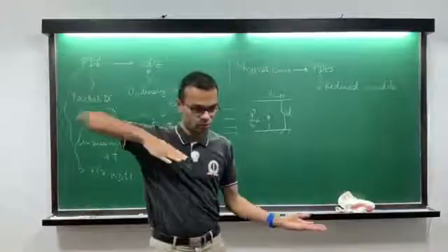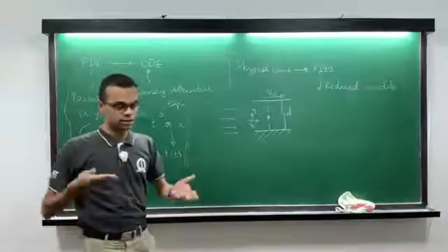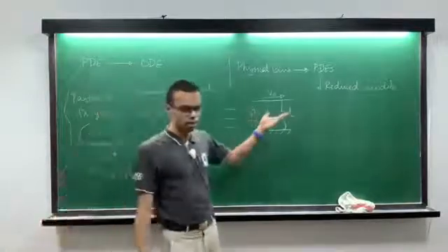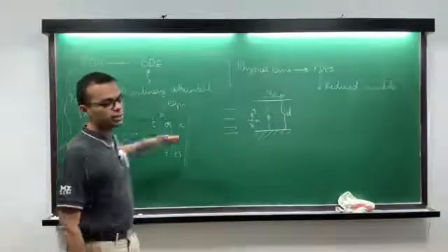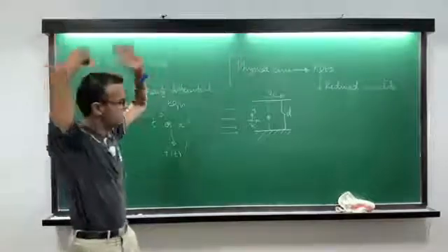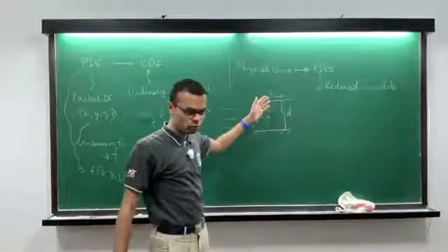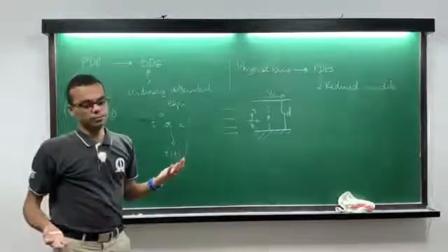Okay, so I'm continuously moving this top plate, but I'm not interested in the transients. Presumably transients happen very quickly. The nature of the fluid, I know that a priori, and I'm not interested in the transition. I only want to know what the final profile is as t goes to infinity, very large t. After a very large t, presumably this profile will be the same here. Okay, what does that profile look like?